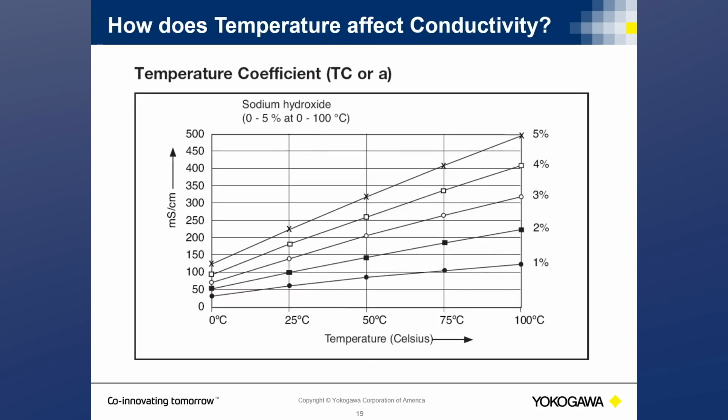Just like other measurements, conductivity is also temperature dependent, and therefore temperature compensation is needed. Temperature also affects the mobility of ions. Higher temperature means the ions move faster, resulting in a false high conductivity reading. Because of this fact, conductivity sensors include a temperature electrode to compensate the process temperature back to a standard reference temperature value. Usually this is room temperature, so 25C or 77F. Without this compensation, any temperature changes would appear as a change in the conductivity value.